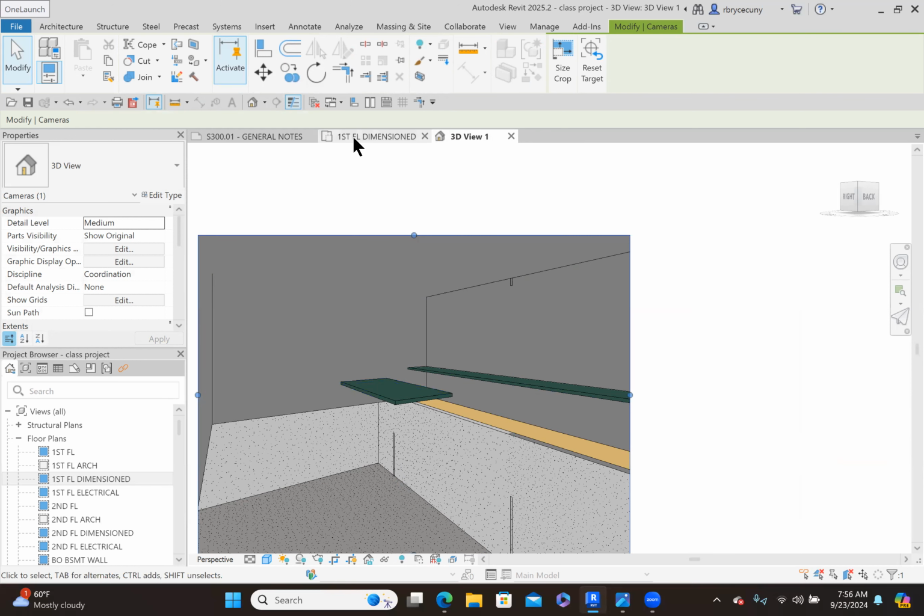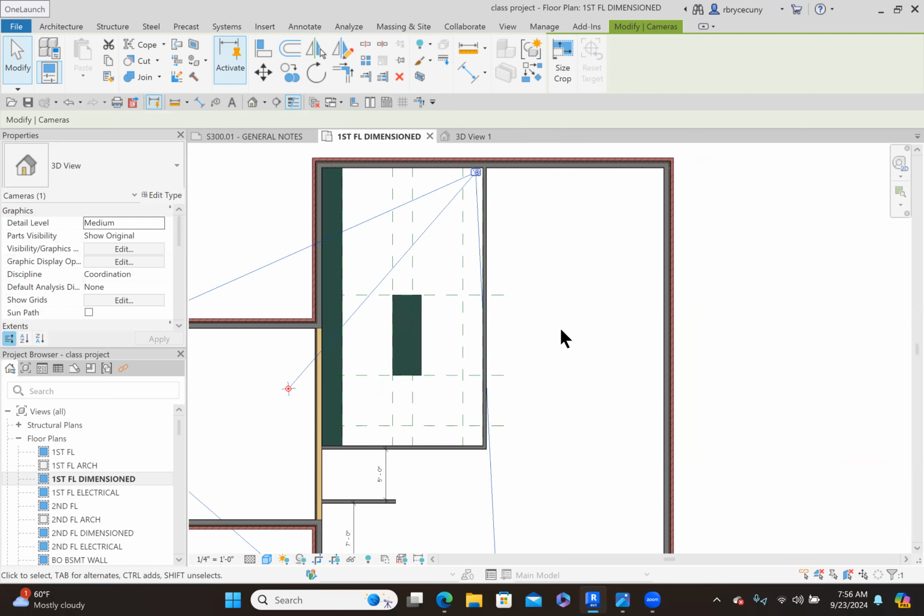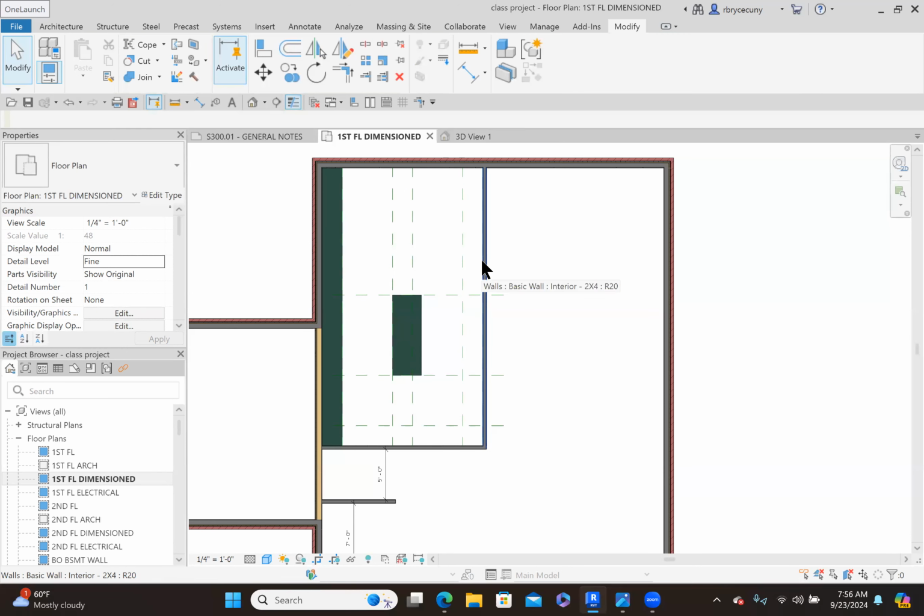I don't recommend putting in the floor till you're sure that the walls are exactly where you want them to be. Because if you put a floor in and it's related to this wall, you can lock it. I don't recommend that. Meaning that you could lock your floor to this wall so that when you move the wall, the floor moves too. I prefer to get the wall in correctly first. I think it's all right, but I'm not sure.